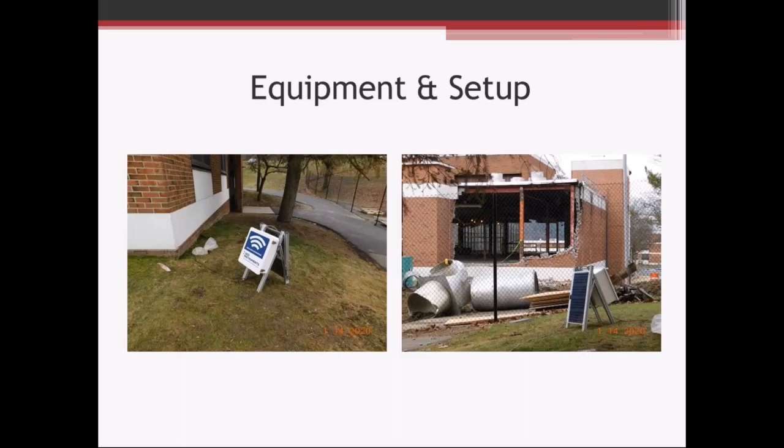Here's a setup. Here's the geophone. You can see the geophone wire going to this hole right here, and that's just a sandbag we've got over the geophone. It's pretty much right at the corner of this building. Taking a look behind me, you can see right here, this is the work that we're monitoring. There's a little bit of demo work going on right here. Here's our seismograph, and the sandbag right here. So we're monitoring demo operations right here. Later on in the project, they were driving some piles, and we were monitoring that as well.